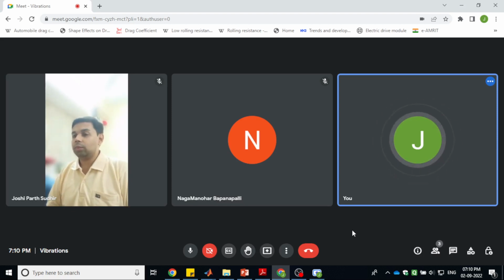We saw this with respect to a quarter car model example, where we model the car body and the stiffness and damping characteristics of the suspension, and the wheels, their inertia, stiffness and damping characteristics. In that model we saw how the response of the system can be obtained using MATLAB.